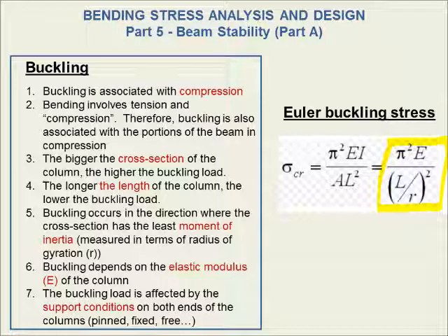And we put it in bending, and there's a certain portion of it that is in compression. That portion is going to reach a buckling stress, right? Which is not exactly this buckling stress that we see. It's not exactly going to go in this manner, because over here we're looking at the entire cross section, but for bending only a portion of the cross section is in compression.